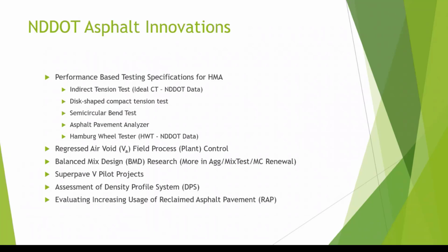Because if you came through pavement inspection class when I was teaching it, we talked about asphalt binder as an important factor in density, because when it's hot, asphalt binder works as a lubricant, which means that it'll help reorient that mix under the screed, under your rollers, compared to a lower asphalt content mix that doesn't have as much lubricant in it. And then, of course, as that asphalt cools, it becomes the glue or the cement for the mix.